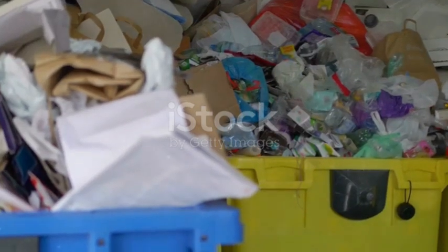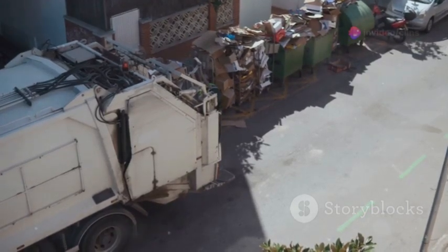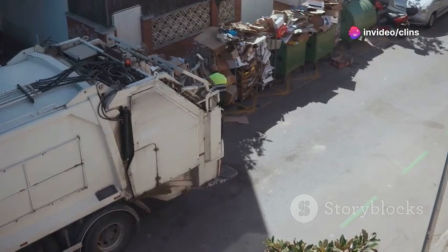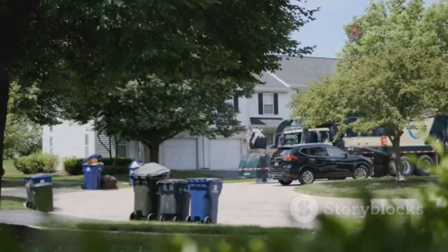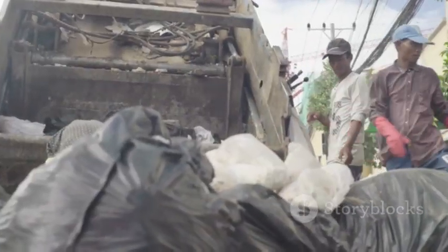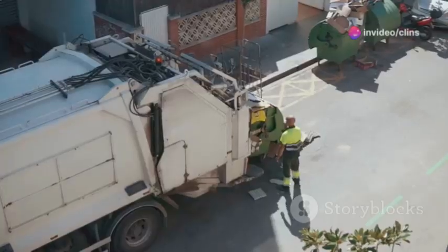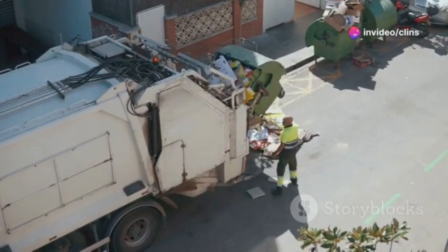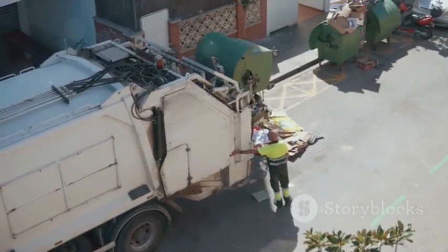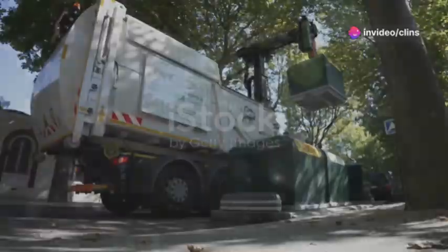Stationary container systems. In this system, containers remain at the collection point, and only the waste is transported. There are different types. For instance, curbside bins, which are small bins used for residential waste. Then, we have dumpsters, which are larger containers for commercial or multifamily residential buildings. The advantages include lower transportation costs and efficiency for frequent collection schedules. However, there are disadvantages. It requires regular maintenance and cleaning, and there's limited capacity for large waste generators.